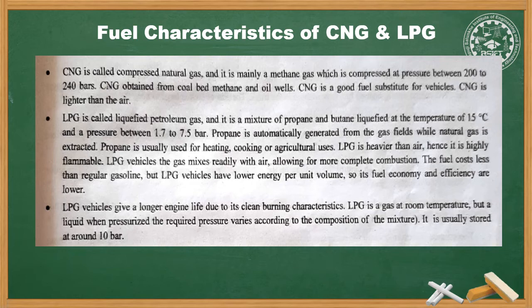In LPG vehicles, the gas mixes readily with air, allowing more complete combustion. The fuel costs less than regular gasoline, but LPG vehicles have lower energy per unit volume, so fuel economy and efficiency are also lower. LPG vehicles give a longer engine life due to their clean burning characteristics. LPG is a gas at room temperature but liquid when pressurized to the required pressure, which varies according to the composition of the mixture. It is usually stored at around 10 bar pressure.